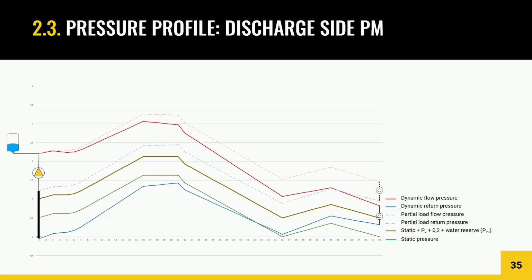Here you see the effect when pre-charge or system pressure has fallen and there is real heat demand at full load. So at full load, the pump creates its maximum differential. So the maximum differential can be seen here. If the reference level has dropped, through loss of pre-charge or system pressure, the entire pressure profile will shift downwards. Discharge pressure is lower than intended. Suction pressure drops even further, potentially approaching atmospheric pressure at high points in the circuit. This increases the risk of air ingress, local evaporation and cavitation in the pump suction, leading to noise, instability and reliability issues.